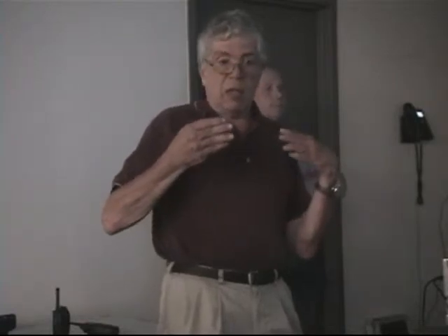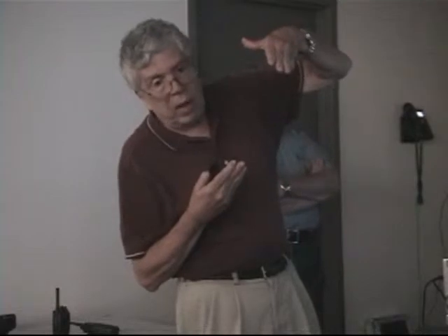So, what happens is that forward error correction does the best job it can, then it hands the data off to the vocoder to reconstruct. And what it tries to do is say, if there's something missing or the data is corrupt, now look at what was I doing before I got to the bad part, and what am I doing after the bad part, and I'll fill it in as best I can.